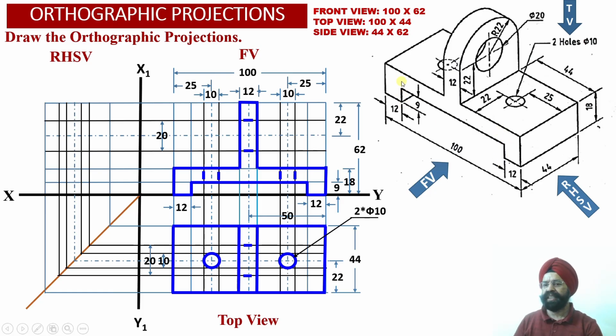And another thing we should observe, here we have got these two vertical surfaces. So this vertical surface and this vertical surface are projected as edge view projections into the top view projections as hidden line projections, because this surface and this surface are not visible to the observer from the top. So we are going to obtain hidden line projections corresponding to these two vertical faces of the rectangular slot which is available with us onto the base of this horizontal web.